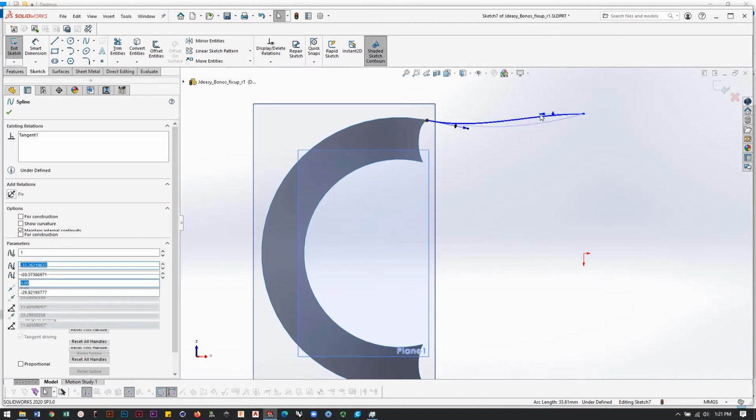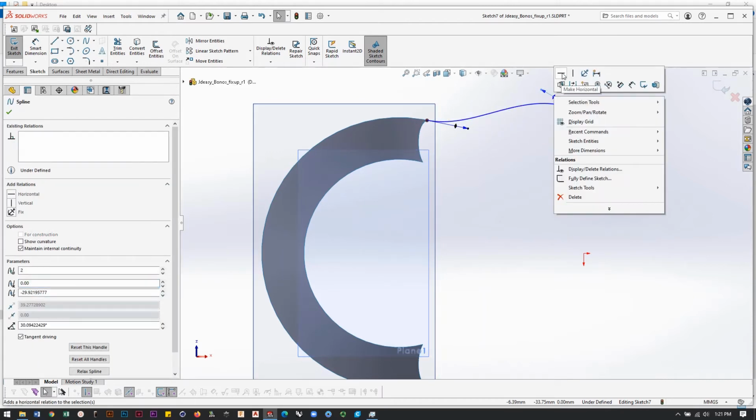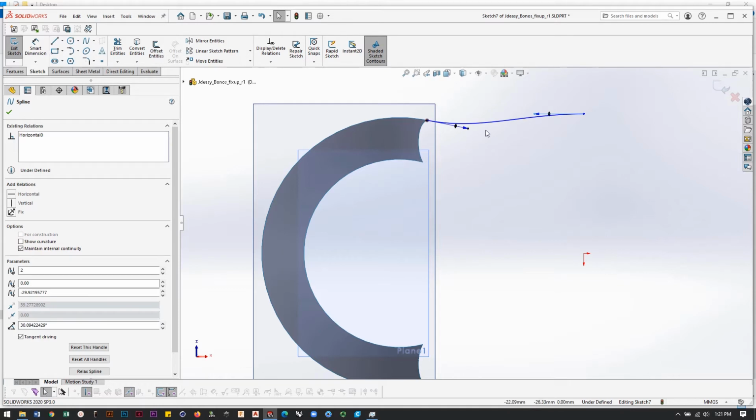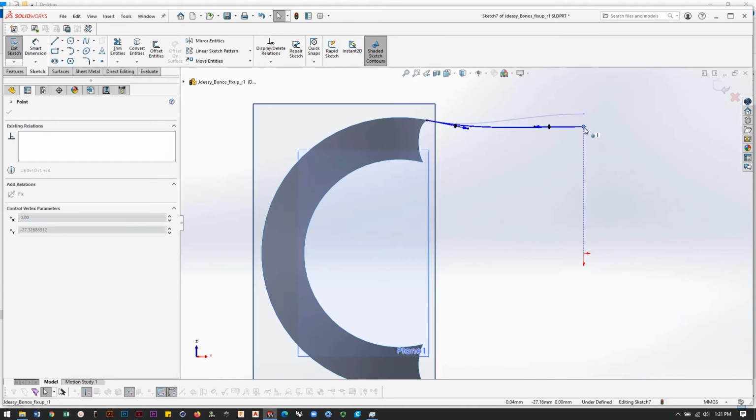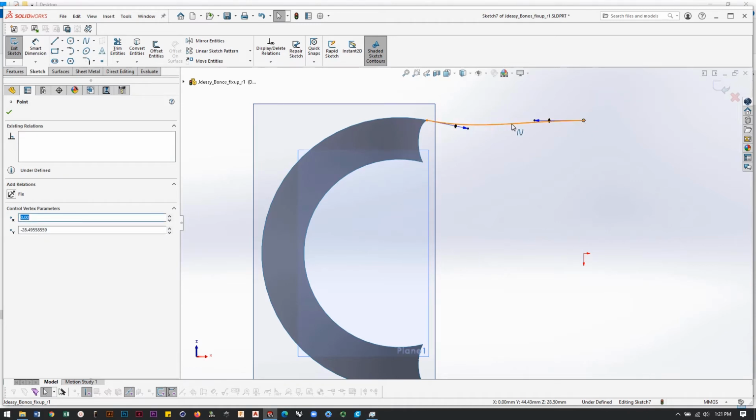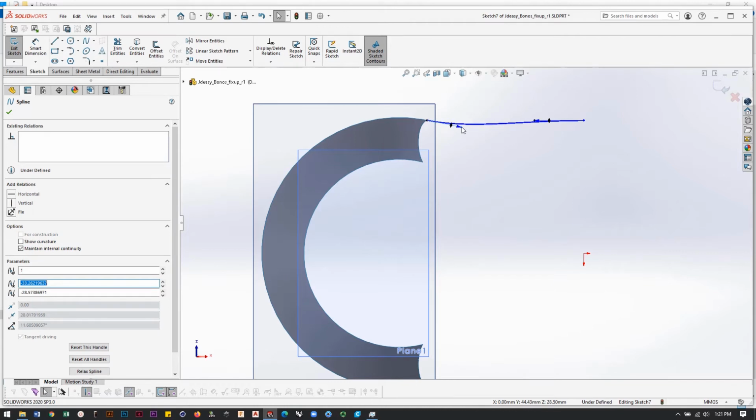This side, just pull this up and flatten it out, and make it a really smooth, sort of almost flat arc here. With the tangent setting on this edge of the curve, you should have the ability to flex this curve a little bit more, because the tangency blend is a less intense blend, and so it gives you a little bit more flexibility in the curve, which is nice.